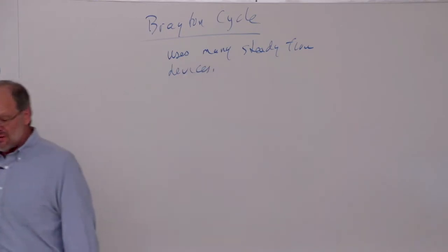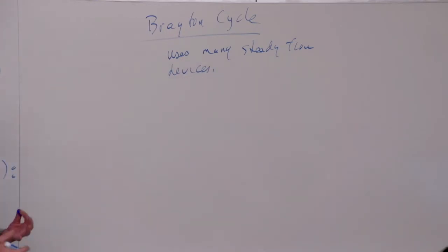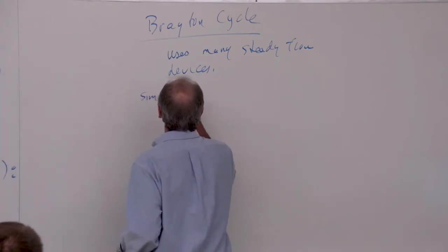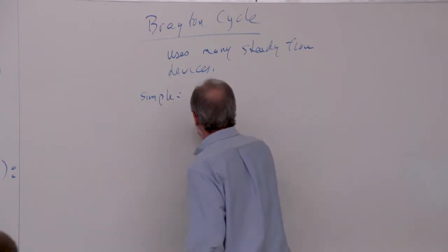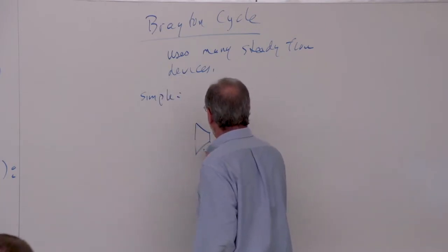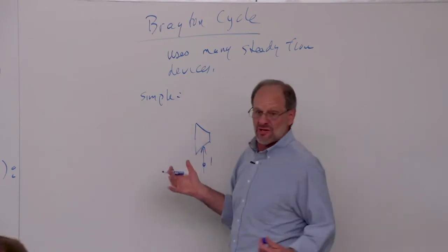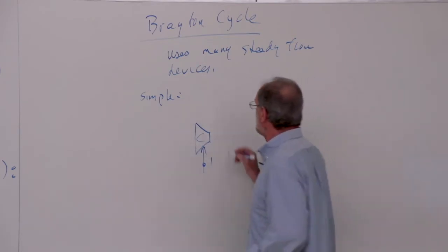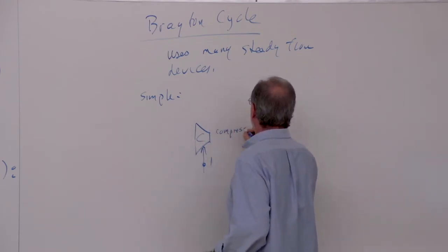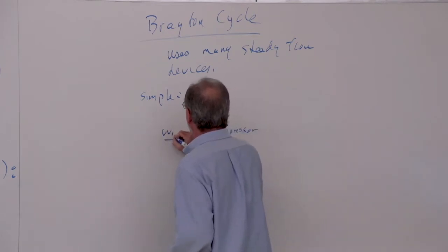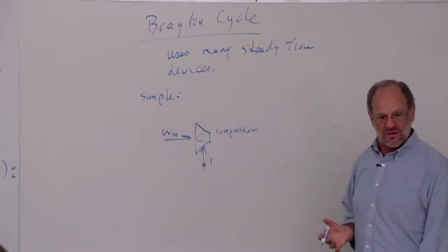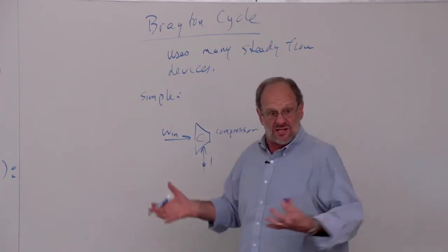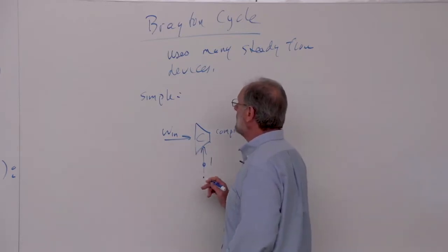Okay. And perhaps the best way to begin something like this is just to show a nice, relatively simple schematic. So again, this is just the simple Brayton cycle. And in a typical simple Brayton cycle, we'd start at state point 1, and we would enter a device that's called a compressor. So I will often just use a big capital letter C, but I'll just write the word compressor for now anyway. So work input is certainly going to come into this compressor. In other words, the air that's moving through the compressor is going to have work done to it, and it's going to compress the air, right? It's going to go to a higher pressure and temperature. So that's our work input.